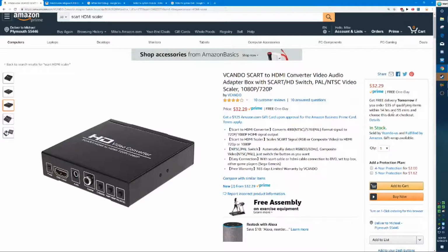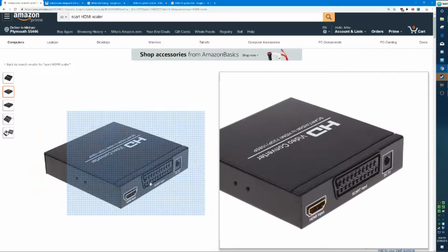So mainly I use these in a Pro AV world, as these are really a great Swiss Army knife video converter for any person dealing in Pro AV. As you can see here, they have both a Scart input and HDMI input. And over Scart, in the NTSC domain, it gives us the option for component input, and in the PAL region, it gives us the option for RGB. However, both RGB and component work in both PAL inputs and NTSC style inputs on the specific adapter.